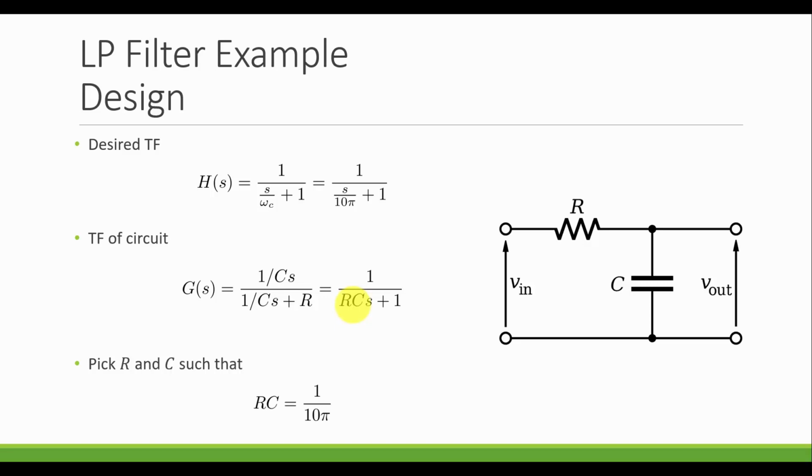Now, there's a whole range of resistors that we could choose, and a whole range of capacitors that we could choose. If we were actually going to build this, we would probably target some capacitor that we wanted to use, since they're going to be fairly small values in the millifarad or microfarad range. That's going to be more of a limiting hardware design choice.